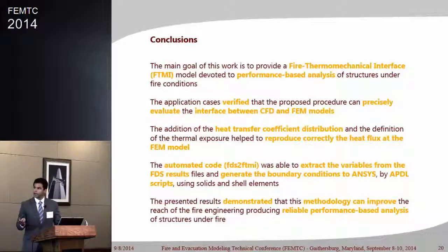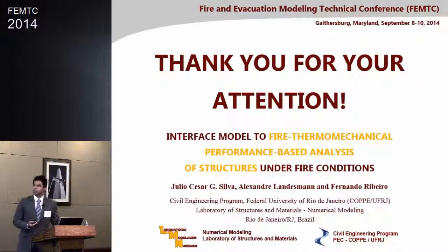This automated code, FTS to FTMI, which is now available at the FTS repository, was able to extract the variables from the FDS result file, the boundary files, and generate all the boundary conditions needed in ANSYS by APDL scripts using solid and/or shell elements. And the presented results demonstrated that this methodology can improve the reach of fire engineering, producing reliable performance-based analysis of structures under fire.